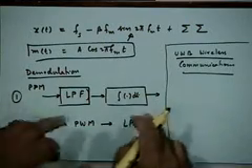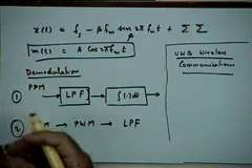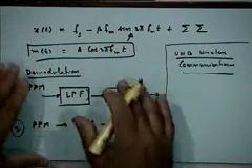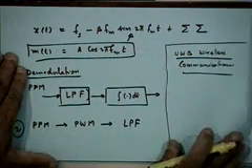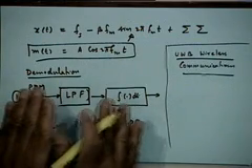And when you do this, since you are transmitting baseband pulses, information in them can be embedded either through amplitude modulation, PAM, or pulse width modulation, or pulse position modulation, right. So I thought I should briefly mention some of the modern flavor about these pulse modulation schemes before we close this topic. But remember, what we have discussed is analog modulations. We discussed analog modulation of sinusoidal carriers earlier, and we discussed analog modulation of pulse carriers here, right.